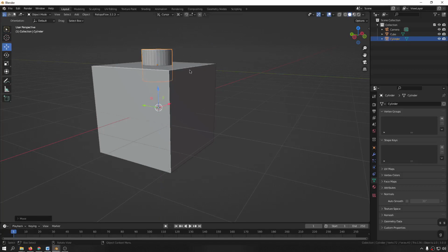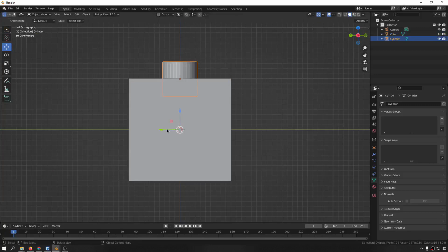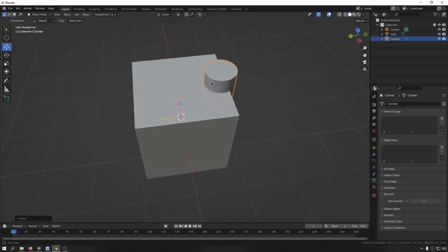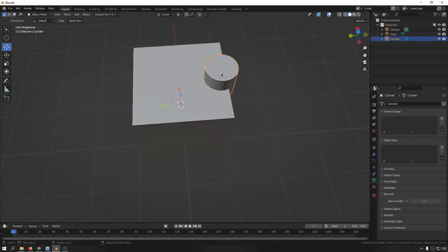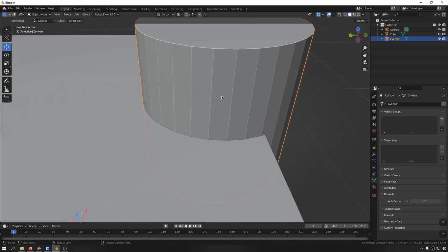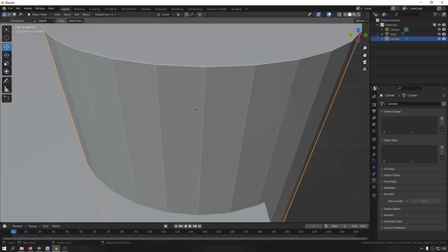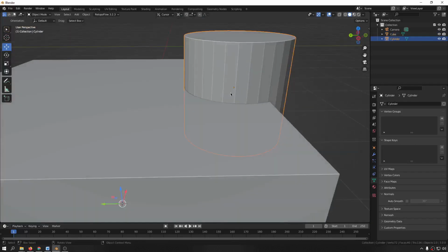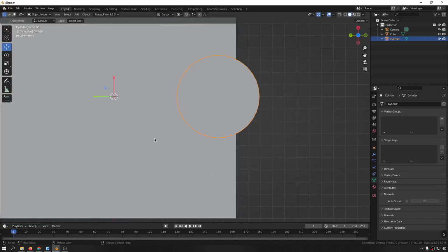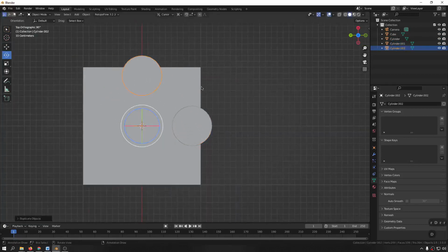For example, if we want to add it into here, do bevels and do all kinds of things. And let's say that, for example, we want to duplicate this around. So we select it, and now the pivot you see is in the center of this, but now the pivot is showing in here. You shouldn't be fooled by that. We select it, we select this, and now we are seeing the pivot, and hit Shift S and origin to cursor in here, and now go to top and Shift D, bring it in here.